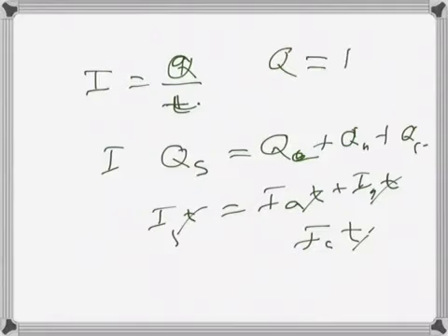And from charge we get this equation, because Q is It, again from the very definition of current which I talked about in the previous video. So from there we get Kirchhoff's current law. So the algebraic sum of entering currents, or we can say leaving currents, at any node will be equal to 0, and that's how the law goes. So yeah.